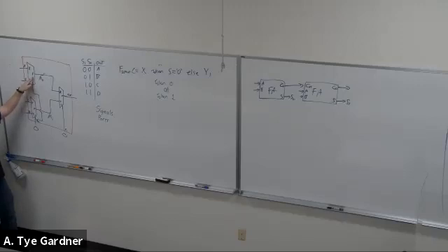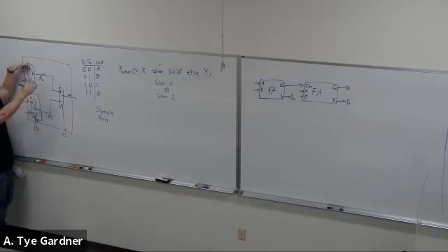So in order to do this, there's a couple different ways, but this mux doesn't have to know that M0 exists in this architecture yet, okay? There's logic inside of the mux, which is behavioral, which I'm building now. And then there's a structural, which is going to need the M0 to tell that how F is connected to this X, okay?